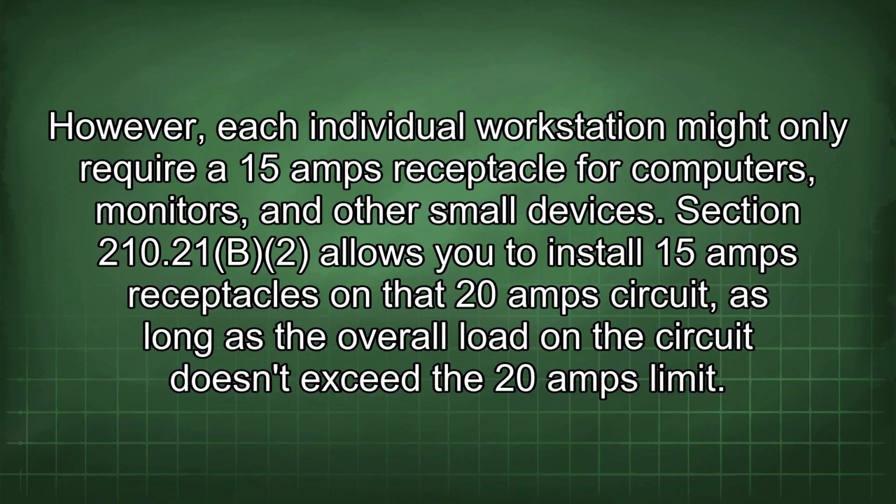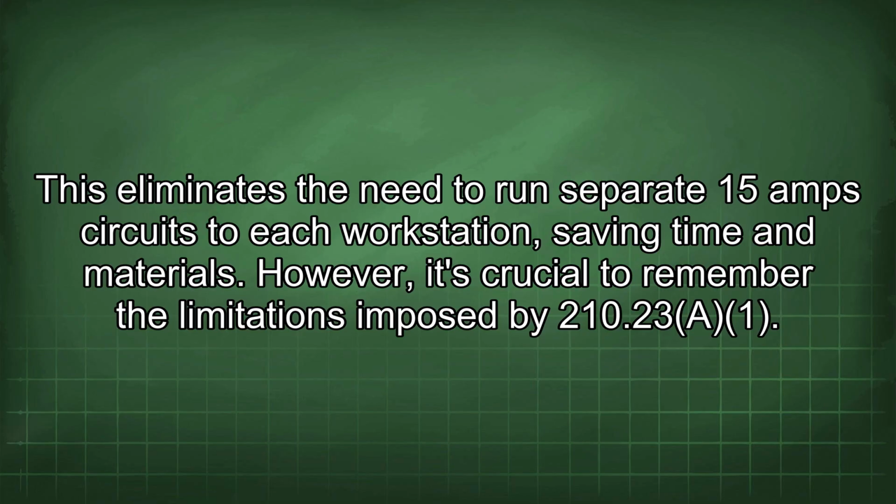Section 210.21 allows you to install 15 amp receptacles on that 20 amp circuit, as long as the overall load on the circuit doesn't exceed the 20 amp limit. This eliminates the need to run separate 15 amp circuits to each workstation, saving time and materials.